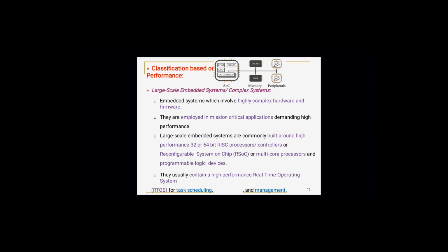So triggering means whether an embedded system needs a particular event to run or it automatically keeps running all the time. Your music player is a triggered system. Whenever you press a button to lower the volume, it lowers the volume. Whenever you change the song, it changes the song. Otherwise, it does not work. So embedded systems are triggered or non-triggered, event based or non-event based.